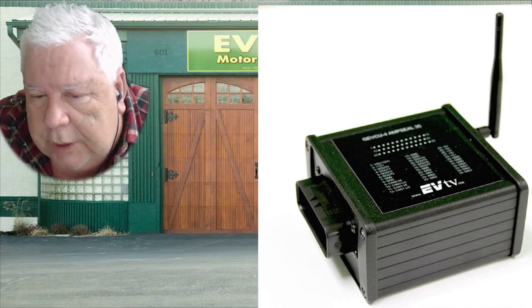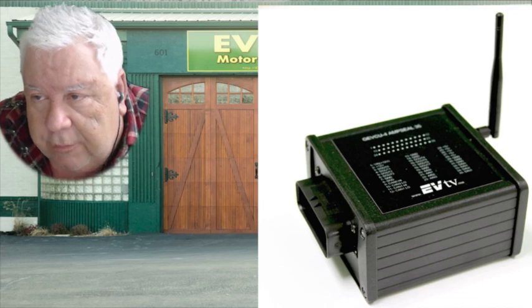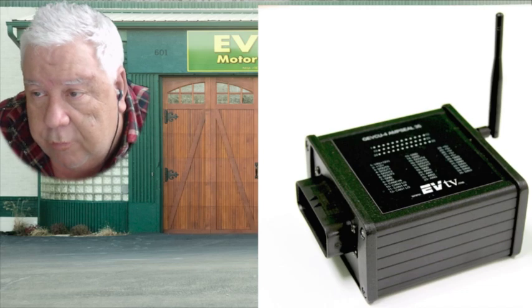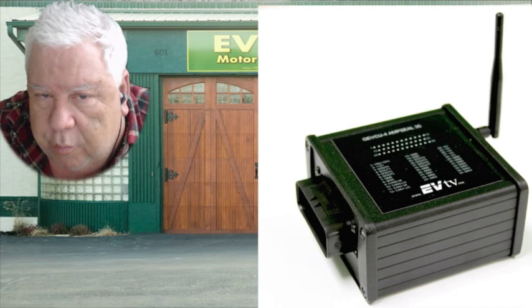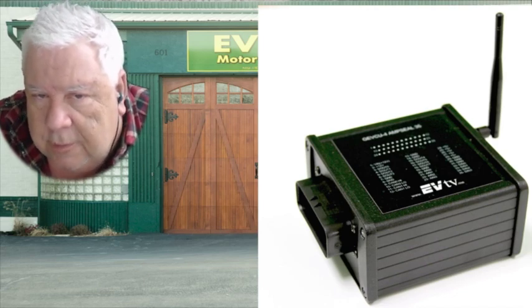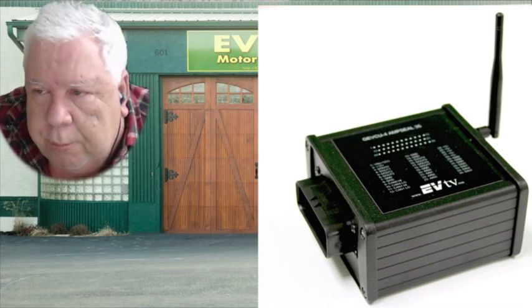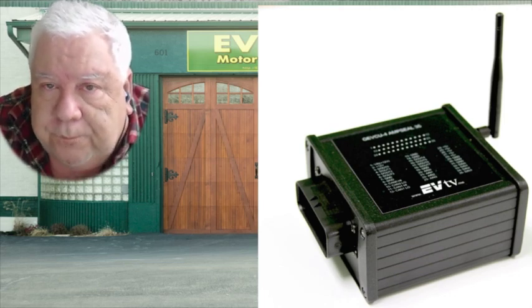And so we decided to launch a program to develop what we call the Generalized Electric Vehicle Control Unit, where it had an interface where you could actually change many of the variables that you want to change, what the voltage is on the throttle input that you want to control the thing, and how much regenerative braking, and how the brake connects, and how to turn on the brake lights, and pre-charge the unit, and many other basic configuration items without doing any software programming at all.